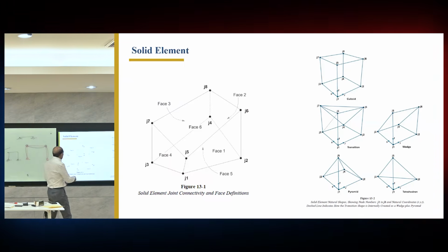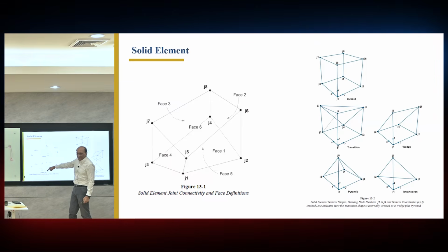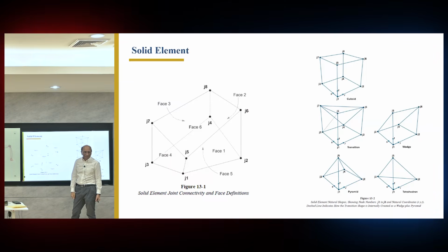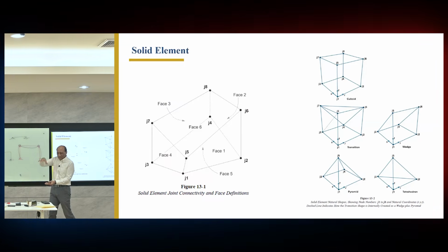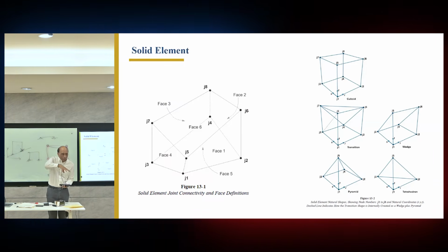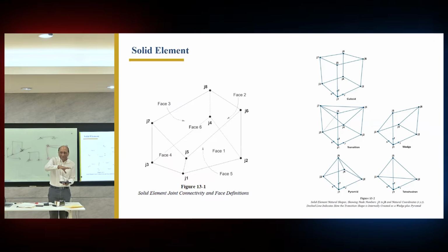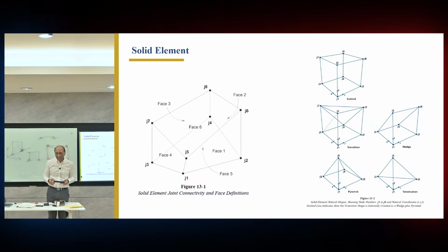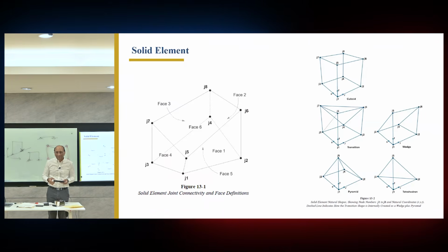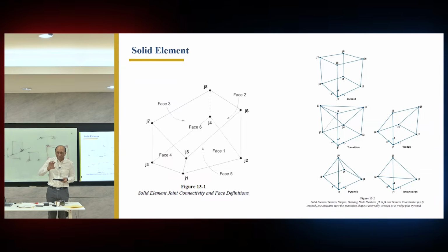The advantage is that they can use one shell element below, one shell element on top, connect them together, and it becomes a brick. And that is so good because they can just extrude, copy this shell here, connect them together, and you make a solid. So they can easily convert a shell model into a solid model by simply extruding by a number of layers, called extrusion.